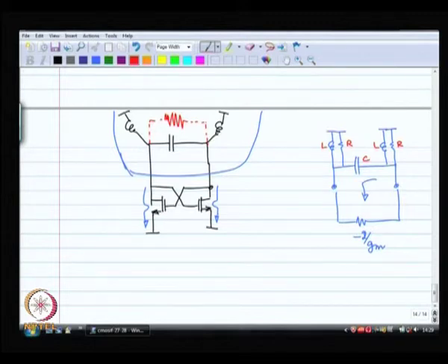First you have to break the cross components. So, the cross components can be broken into series components. So, you place two capacitors of size 2C each in series with each other, and as far as this negative resistor is concerned, you treat it like two resistors, two negative resistors, each of size minus 1 by GM.